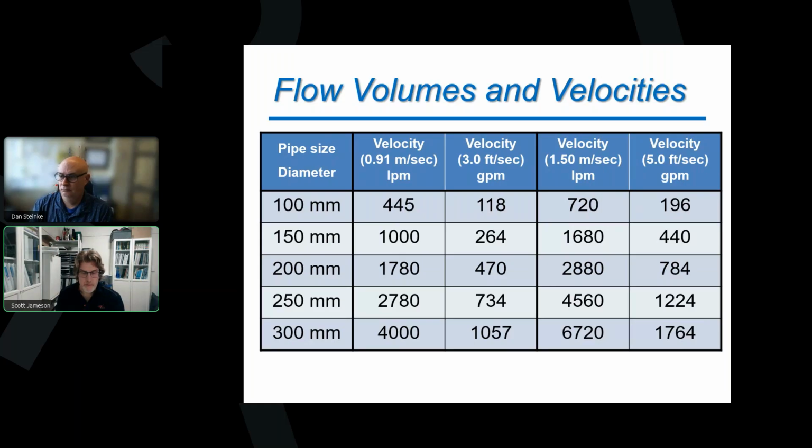Some of them, like the sodium thiosulfate, have problems of being oxygen scavengers. If you want to go to the vitamin C, which doesn't have the oxygen scavenging problem, well, then you're going to have to pay more, right? The cost of that dechlorinator is quite a bit more. So, yeah, you've got to work that out on your individual system.